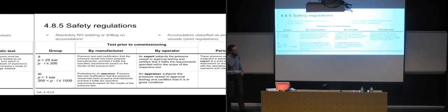So there is no point in having a monthly test if this hydraulic system is in use every other month. You don't need to test it more often than you're using it. So then the expert has to decide that, well, then I'm going to test it every 4 months instead, since we're not using the system that often, for an example.